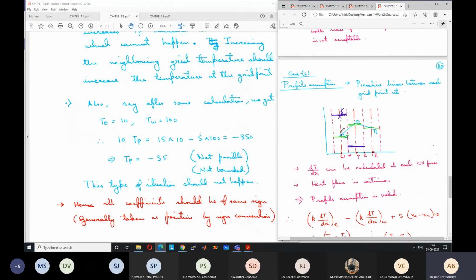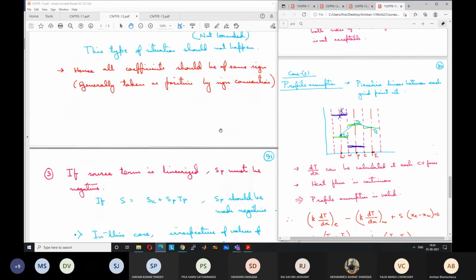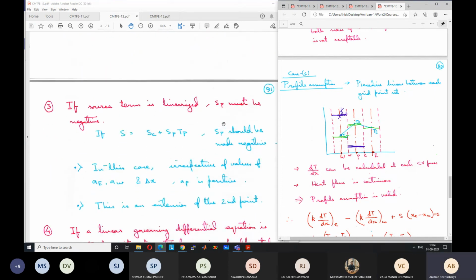Okay. So either flow will come from one side and go to the other side, or flow will come from the other side and go to this side. It cannot happen unless there is a negative source term for the flow here. So if source terms are present, this is not valid, but otherwise it is still valid. Okay. Even if convection is there, artificially you can create this velocity like from here and here, but that is not correct because where will the flow go? Continuity equation will not be satisfied.